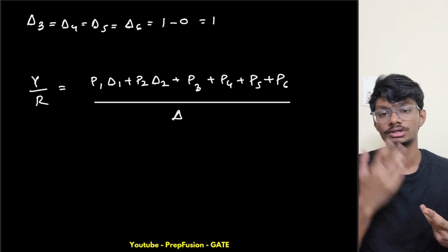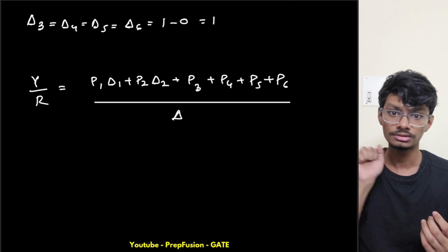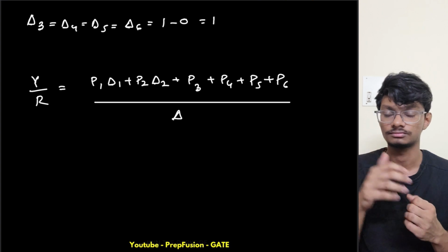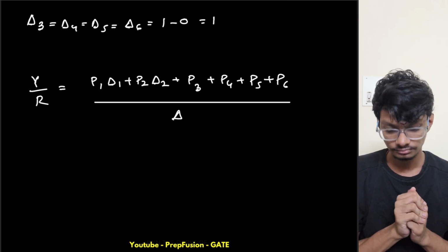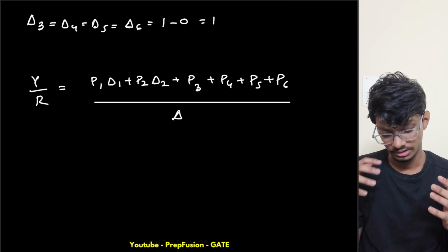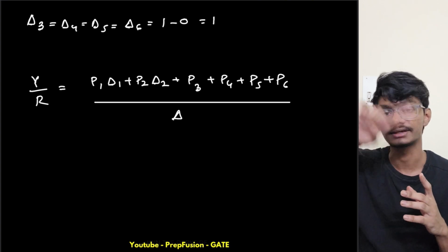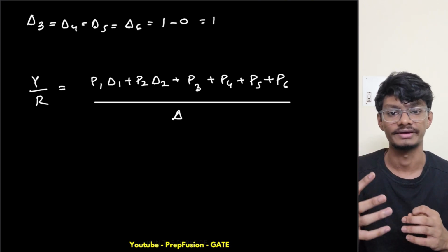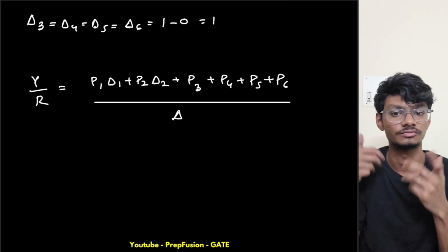So what is happening: if a self loop with unity gain is there anywhere, the equation won't be valid. Now if we have a self loop of any gain at the input, then also the equation won't be valid. Why? Because the input will become 0, which is not possible.